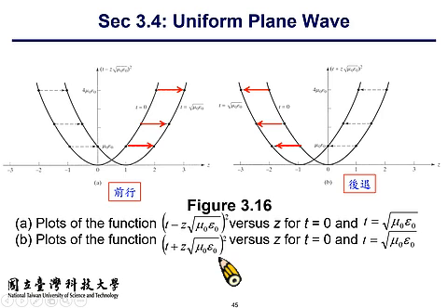Then, to the right-hand side of the equation equal mark, this stands for the velocity of the wave. And it can be represented with 1 over square root of mu times epsilon. So if the propagating medium, the environment, is vacuum, free space, then mu sub 0 is 4 pi times 10 to the minus 7, and epsilon sub 0 is 8.854 times 10 to the minus 12.